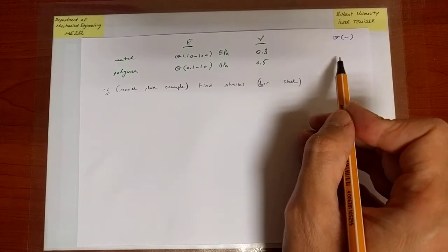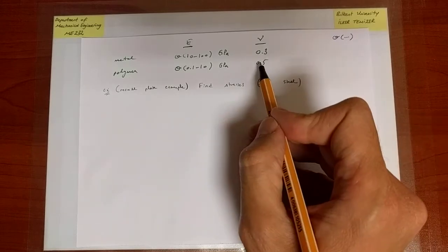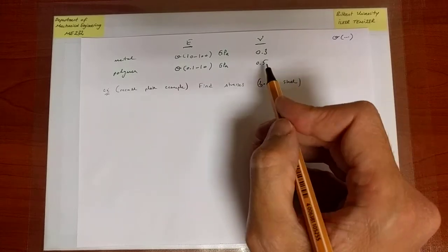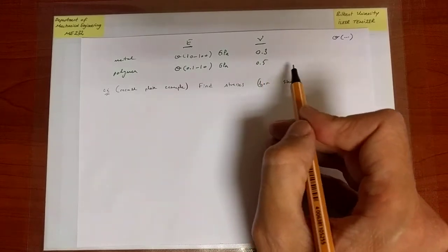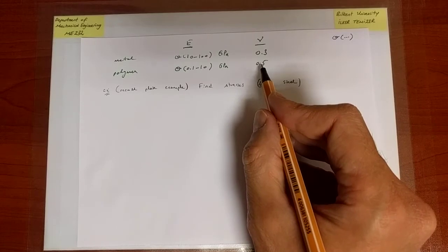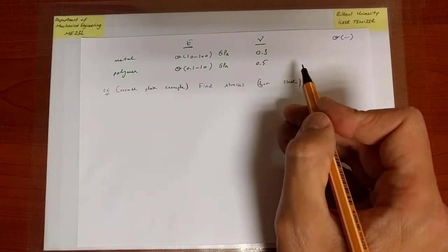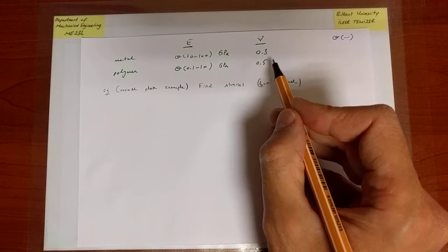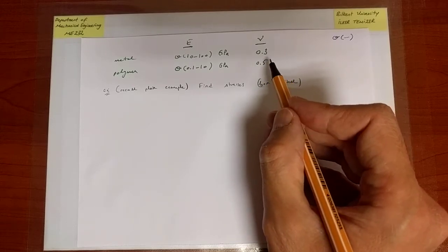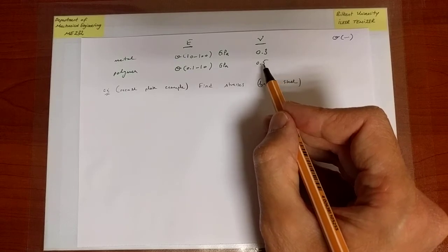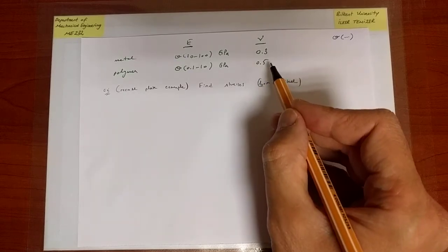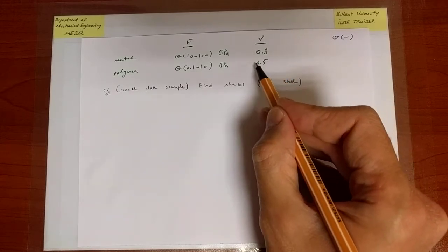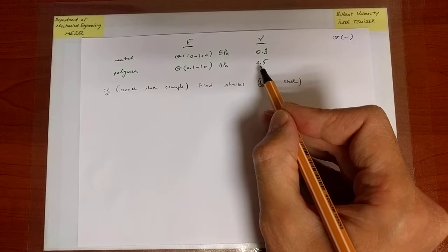If you apply a finite amount of stress, because the bulk modulus is going to be infinite for this Poisson ratio, the volume change is going to be 0. That latter case is what we encounter in practice, which means that for reasonable amounts of stress, polymers are observed to show almost no volume change as they deform elastically. Okay, so this is an expectation that one observes physically, and the Poisson ratio is an indication of that observation.